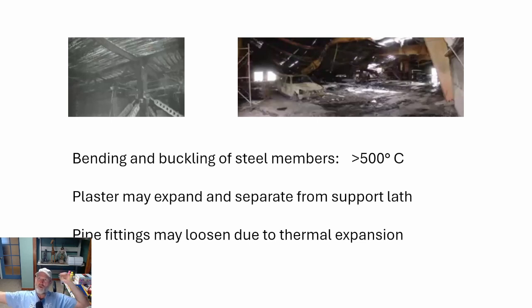So it's on the order of 10 times 10 to the minus 6 per degree Celsius. I think that's about what the coefficient is, 10 or 11. But regardless, using that example of a 100-meter beam, you're going to see a 1 meter expansion for a 1,000 degree increase in temperature. Keeping in mind, 1,000 degrees Celsius is typical for a flashover condition. So you don't need a lot of expansion or a long beam to move quite a bit in the event of a flashover related fire.